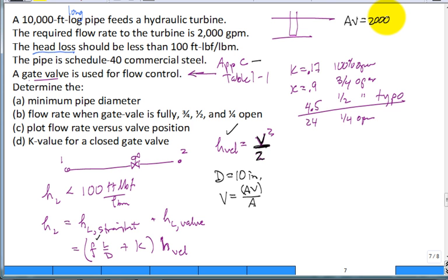It's 0.1336 something cubic foot per gallon. So make that conversion, then convert my minutes to seconds, and I'll get so many cubic feet per second. Then I'll divide by the area in foot squared and get my speed in foot per second. True? Didn't lose anybody.